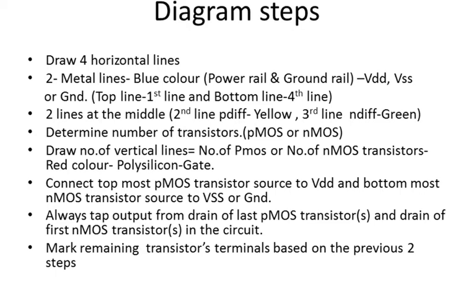This we can see later in this video itself. Always tap the output between the pull-up network and the pull-down network. In the pull-up network, the bottommost PMOS transistor drain is taken for consideration, and in the pull-down network, the topmost NMOS transistor drain is taken for consideration.